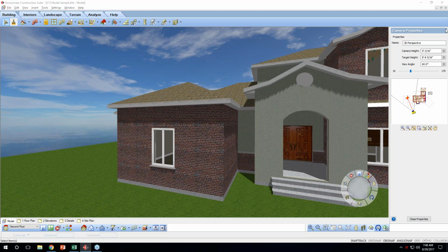So as you're going through and doing that truss run, as you're coming up against the hip or a gable, it's going to change the configuration of the truss itself, looking at the shape of the roof above and the shape of the roof below on the truss run itself and the shape of the chord.